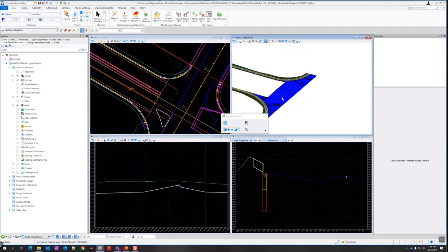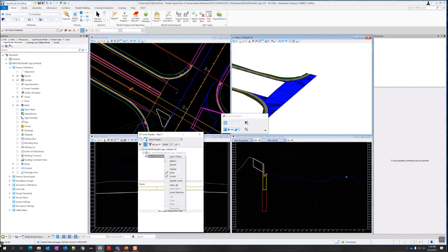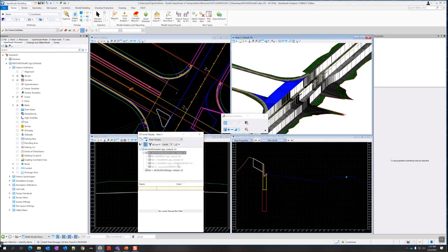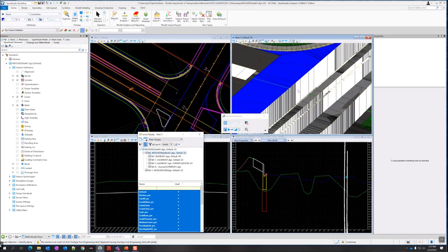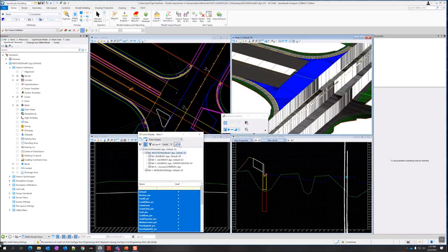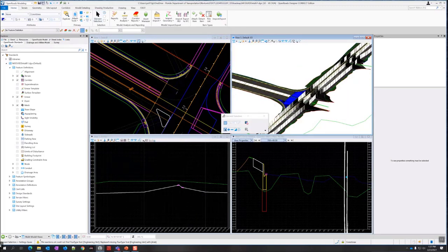Well, actually, I should probably turn these back on before I close that out for the 3D view as well. So I'm going to check display for that and display for the main line 61. And because constructions are turned on, you see all these end conditions here. So it just gets a little bit messier having those on. And we don't need the survey. We don't need the super elevation 3D view. Let's turn that off. And save settings, since I made a whole bunch of display changes right now.